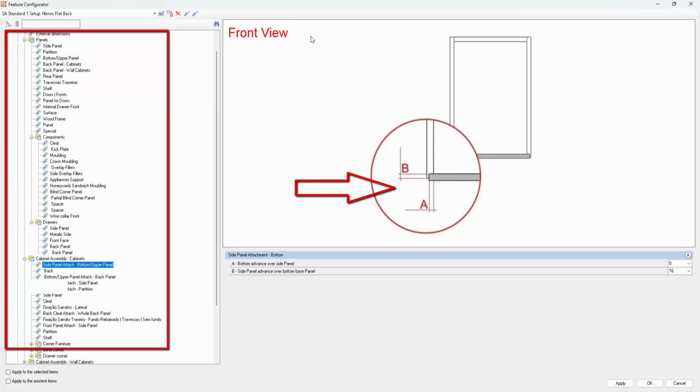And if you look further down, where I've got B, the panel, I've got it as 16 and I've got A as 0. Basically what I've asked this to do is to run my B panel, which is a side panel, all the way down. So if I had that 0, it would stop at the top of where this A is colored. Because I've made it 16mm, it's going to come past to the bottom of this panel. So I'm going to be screwing in or downing, or whichever way you're going to do it, from the side, not from the bottom, from the side.